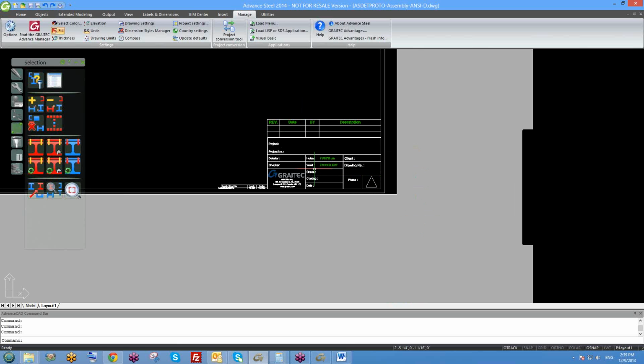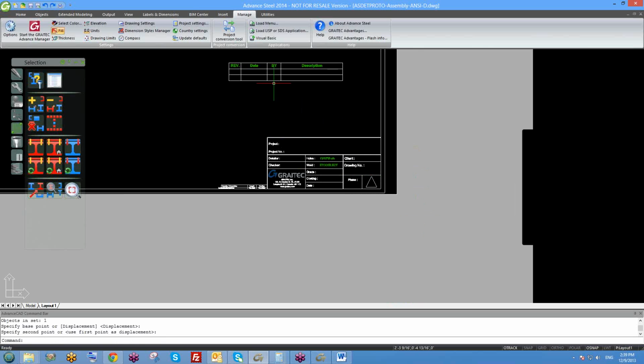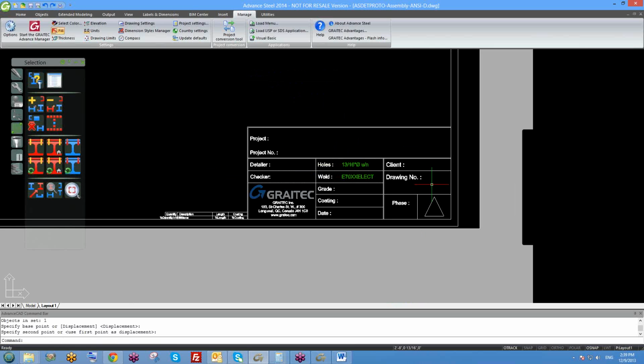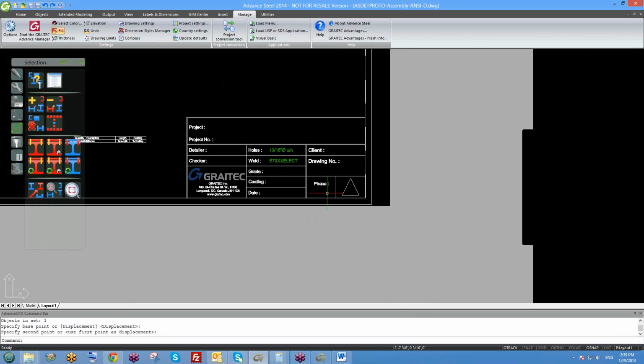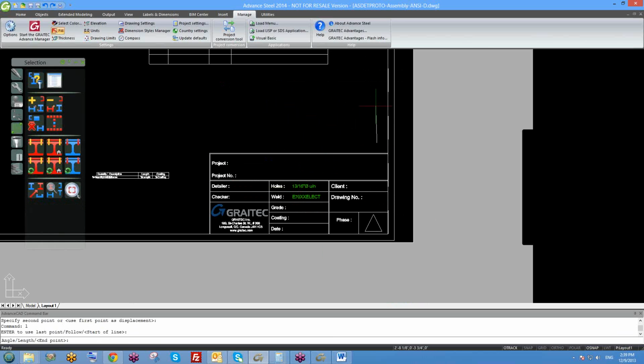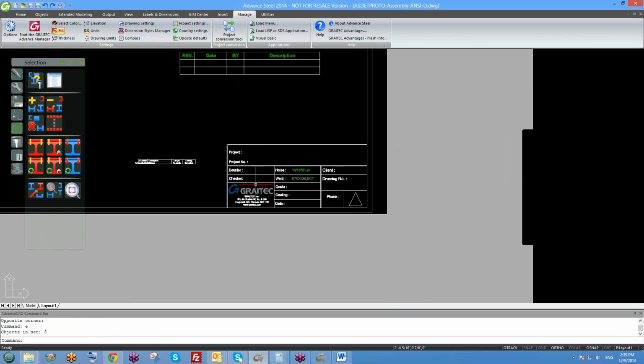And we have this title block. Don't worry about this, move it up somewhere. We're going to modify this part. To modify this part, you again have 2 options. You can recreate your geometry here using line, polyline, everything, like this. I didn't create that right, but you can create your geometry and then use those tokens, or you can use something existing.